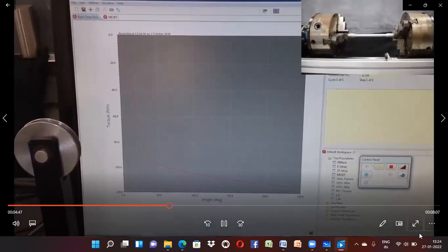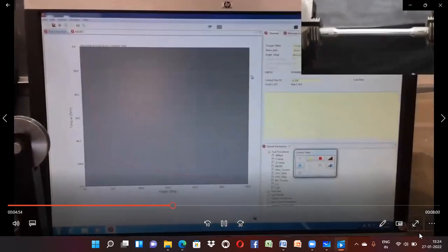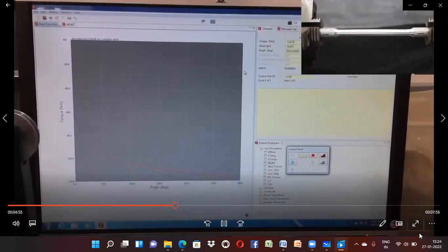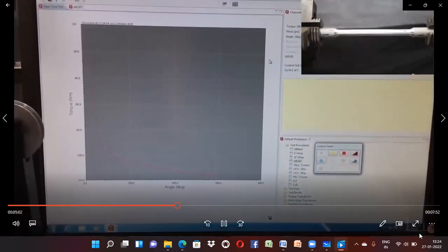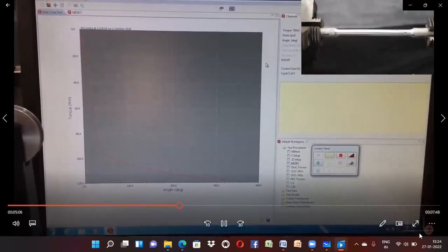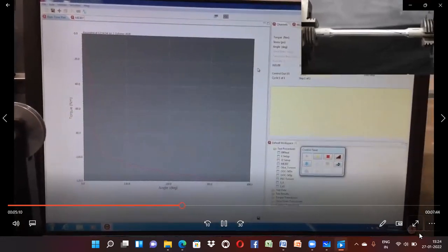There's very high resistance to the rotation at first, and then it drops off, right? As you've learned in 303 or 306, the torsional shear stress is not evenly distributed. It starts on the outside and it works its way inward, which means it's highest on the outside, which means the first place it starts to yield is on the outside.